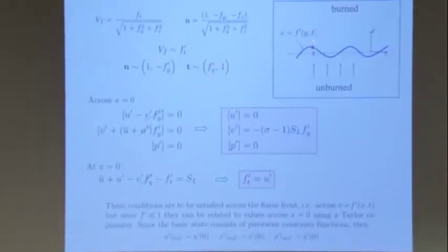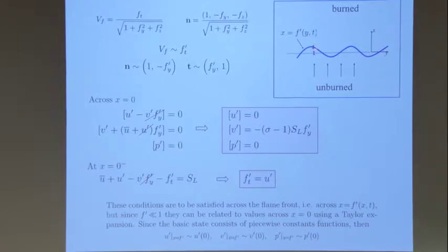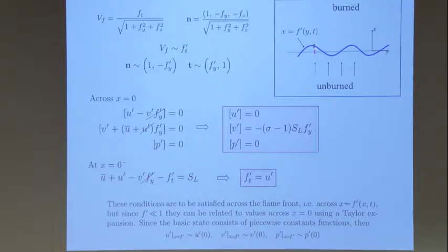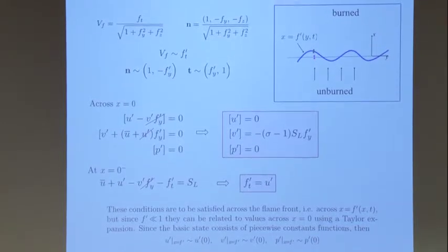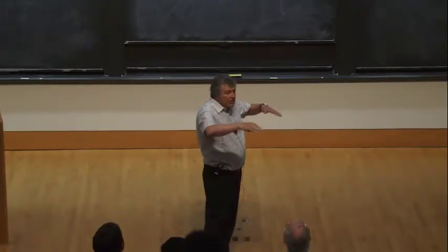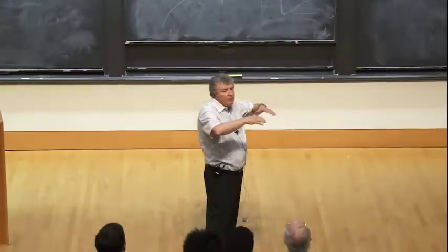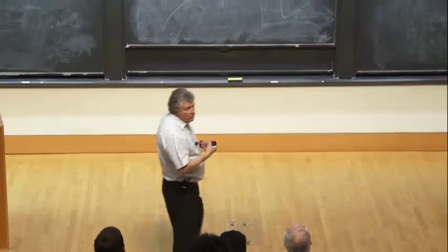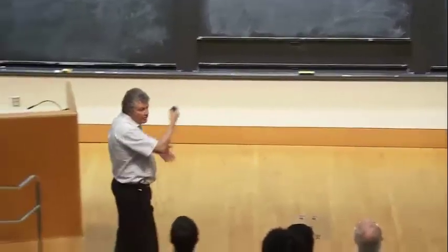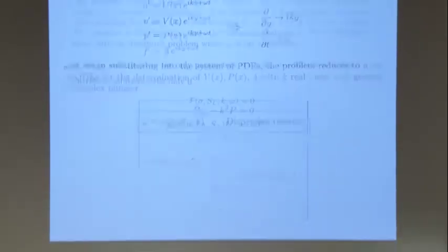And so by Taylor expansion, we can relate the point above to the purple point here above the line x equal to 0 and the one below to below the line. In other words, effectively, we can write the jump relation across the unperturbed flame, okay? Which is mathematically equivalent to the perturbation across the flame itself.